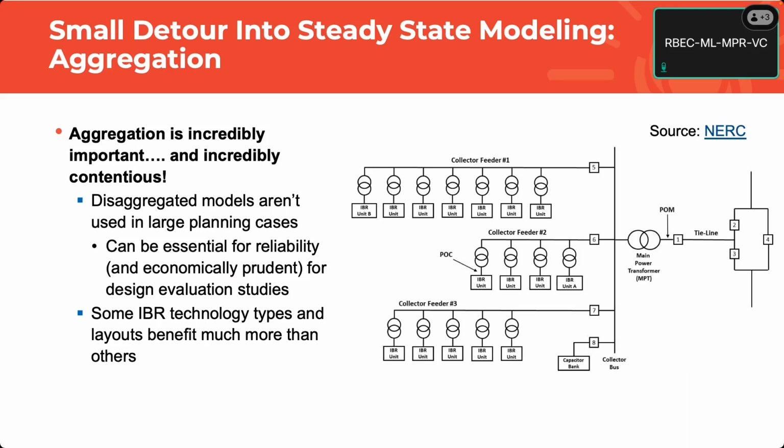Once you've gotten that far, the solutions aren't cheap. What I've done, and maybe you've done the same, is do a detailed study and tap the step up transformers, the unit transformers on the collectors, differently throughout the plant, so they all have about the same reactive power capability. That has a huge impact on fault ride through, because now the taps are all different throughout the plant, so they're all going to see different voltage gains and drops. You could also add more capacitors at the point of interconnection or at your substation bus, which is expensive and hard to do very quickly.